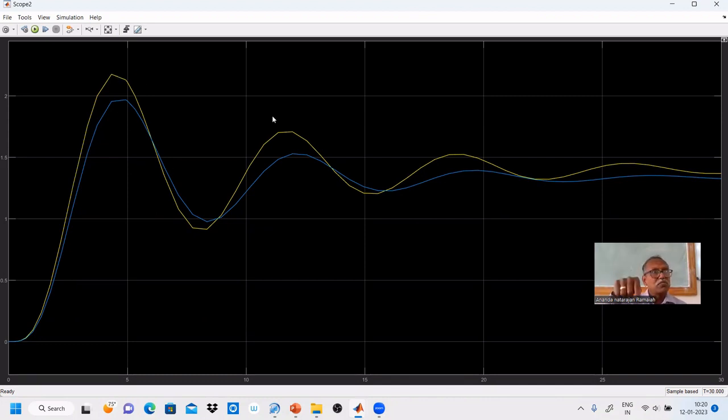In the continuous cycling method, we reduce the gain. That's why overshoot is less. If you reduce gain, overshoot will reduce. At the same time, error will be more. Here you see that gap, the integral of error. That's why error is more, but it quickly settles. Less gain, that's why it quickly settles.